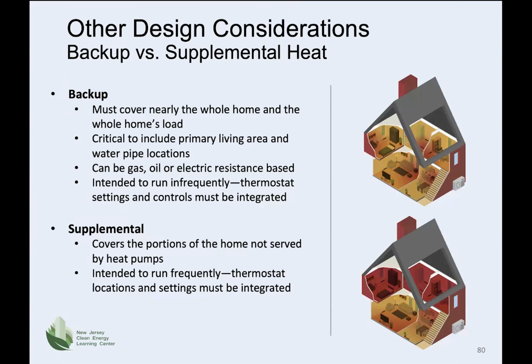The backup system, though, is intended to only run infrequently. And if you do have a backup system, it's necessary that the thermostat and the controls are integrated such that the backup system doesn't run when it's not supposed to. Supplemental heat will only cover a portion of the home not served by the heat pumps. So that's intended to run more frequently than the backup, that is. And the thermostat locations and the settings, again, must be integrated. The heat pump has to work in a coordinated fashion with the backup supplemental heat.